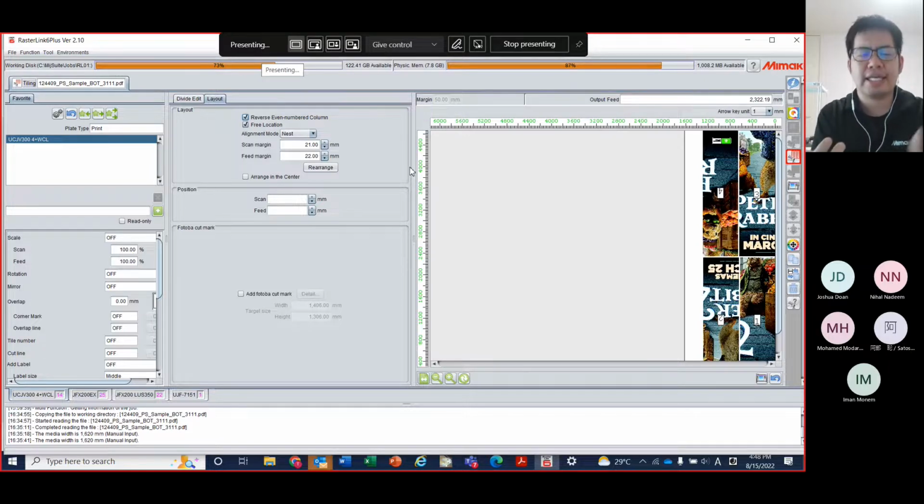So a lot of air is sucked through that open space, which results in the temperature of the right side and left side of the media being slightly different. What's happening is, while printing with eco-solvent or latex ink, which is more temperature sensitive for the colors, you will have slightly different color on the right side and left side. Which means if you make the tiling, let's put it like this.